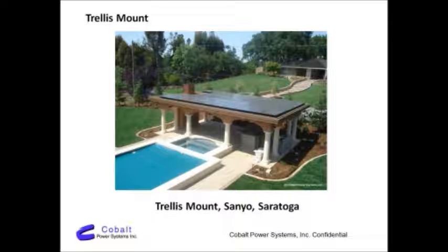First of all, really, one of the big advantages of PV systems is there is almost no maintenance. And we do recommend you wash the panels off about every 6 months. Other than that, really, there literally is no maintenance. We just want you to keep an eye on your inverter, make sure that you have a green light on during the day, and basically you're good to go. 25-year power output warranty on the solar panels.